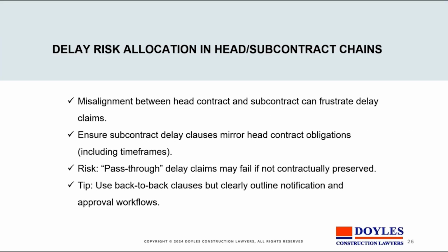I might go to the complexities where you have delay risk allocation that messes up between subcontracts and head contracts. On the one hand, one would think that if the subcontractor is delayed for a day, then the head contractor will therefore be delayed for a day, and therefore the head contractor will grant an extension of time of a day and then claim a day off the principal.